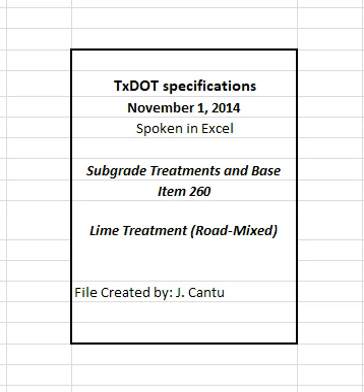Rework, recompact, and refinish material that fails to meet or that loses required moisture, density, stability, or finish before the next course is placed or the project is accepted. Continue work until specification requirements are met. Rework in accordance with Section 260.4.6, reworking a section. Perform the work at no additional expense to the department.